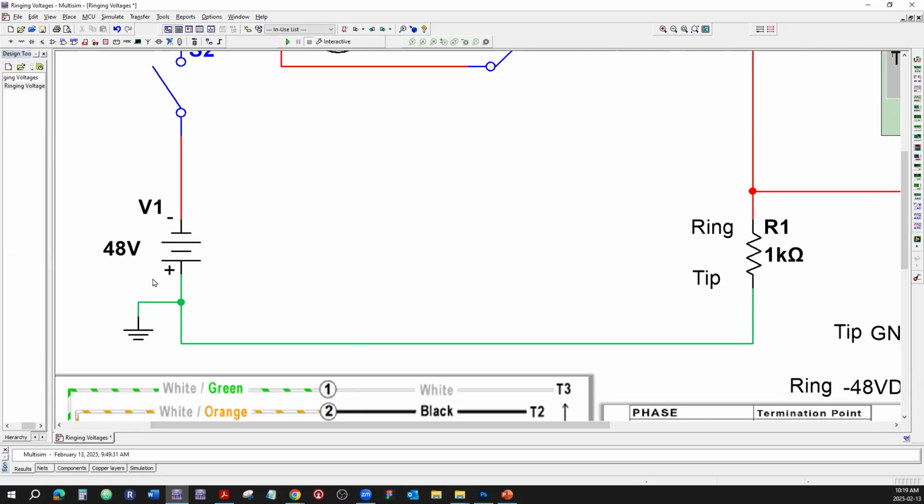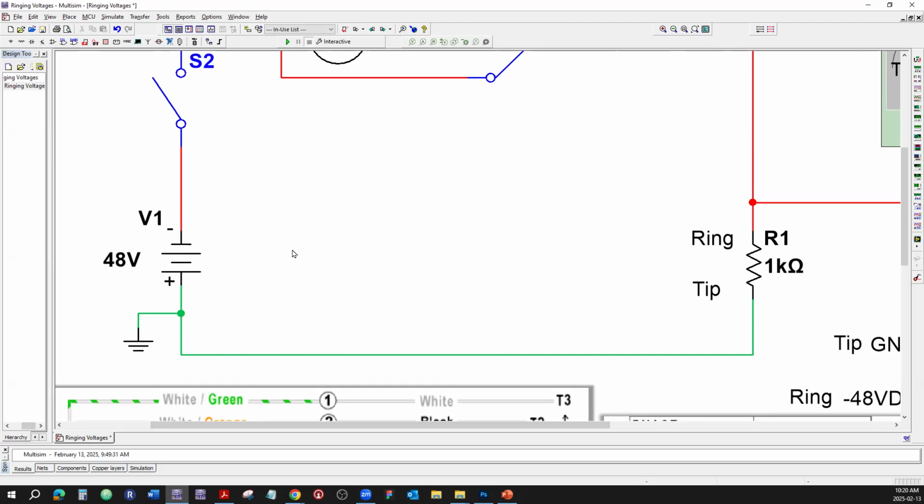So we're looking for, is the battery present, which is negative 48 volts DC, and is there dial tone? If one of them is missing, then some of the circuitry maybe needs to be reset. But that's on the central office part, from the city side, from where the city is. Usually in our area it will be Bell Telephone, Bell Canada. In the States it will be AT&T. In western provinces of Canada there would be TELUS and so on.